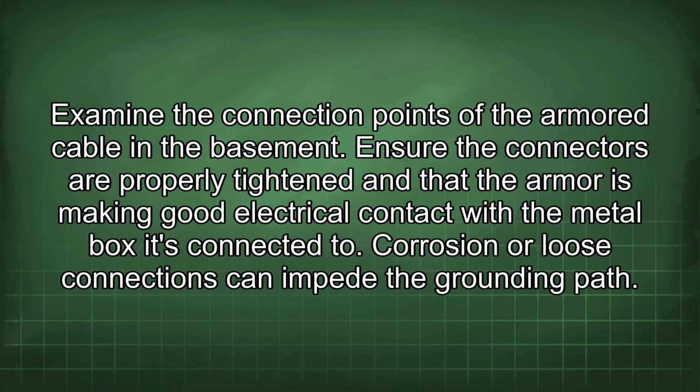Examine the connection points of the armored cable in the basement. Ensure the connectors are properly tightened and that the armor is making good electrical contact with the metal box it's connected to. Corrosion or loose connections can impede the grounding path.